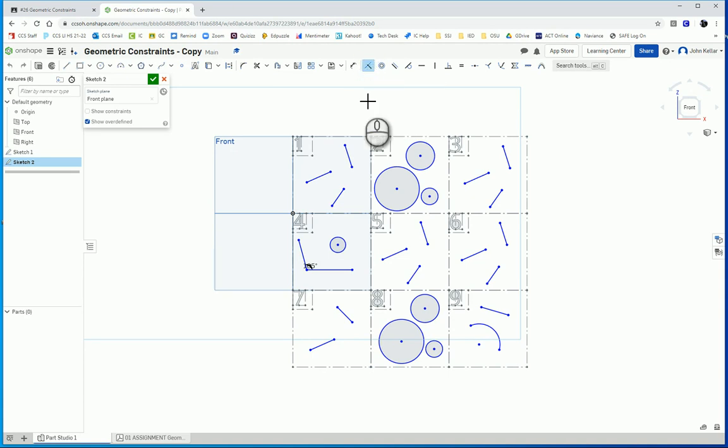So coincident. And we want to make all 3 endpoints coincident at the same place. So we're going to click one endpoint and a second one. And then another endpoint and that same one where the other 2 are joined. Make sure you don't highlight the body of the line segments. That will do something else. We want only the endpoints to be joined. And boom, you're done. Then go on to the next instruction, and when you're done, mark this assignment is done.